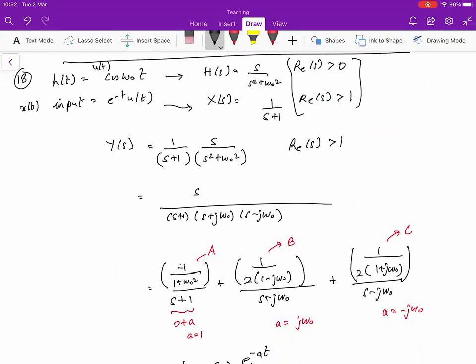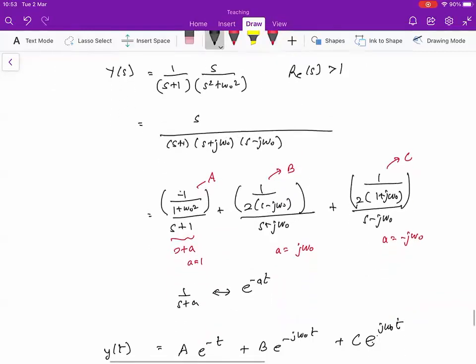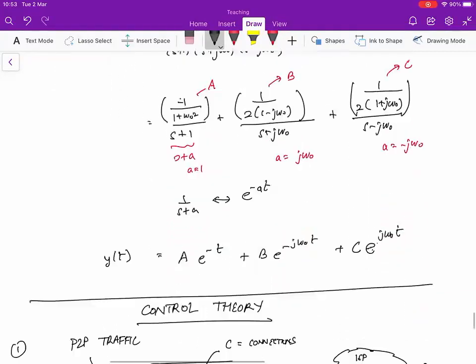So we can just assume for most cases that we add the unit function in front of the transfer function? That's right. Remember, when we're trying to solve the system, it comes into being at time 0, so it doesn't exist before time 0. Pre-multiplying by u(t) is okay because we don't have negative time. We are going from mathematical functions to real systems. In a mathematical function, you look at minus infinity to infinity, but in any real system, it's always going to be u(t). That's a difference between modeling and mathematics.